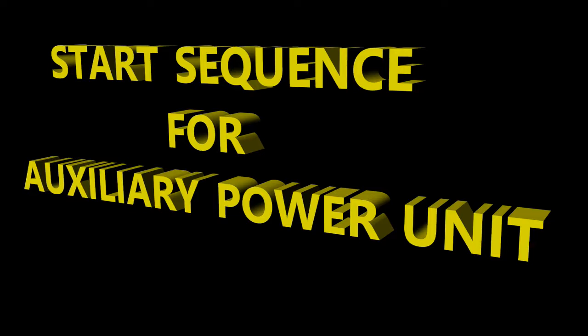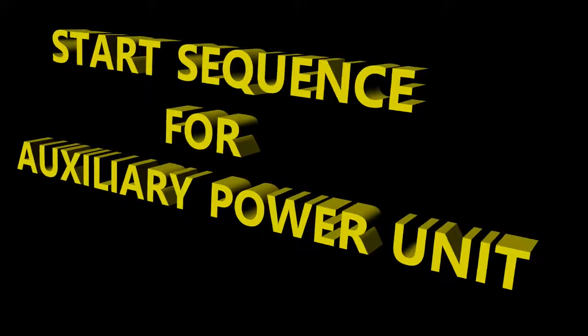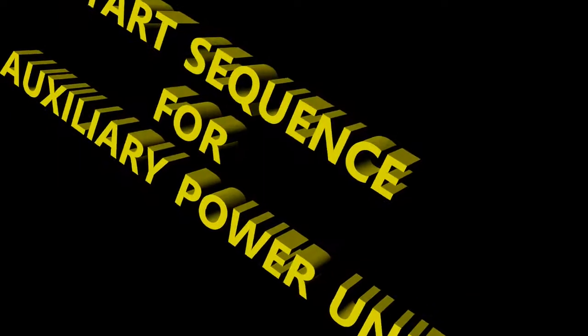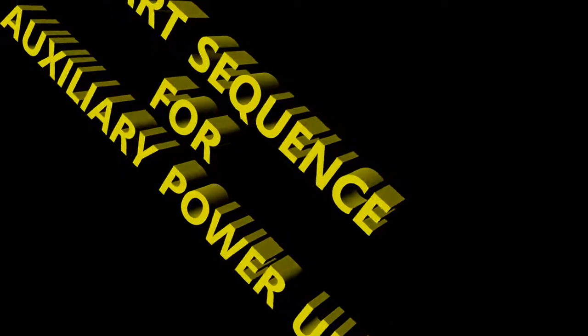At 30% speed, the electronic control box is going to cause what? It's going to cause a de-energizing of the fuel flow divider solenoid. At 50%, what happens? The start contactor is going to be de-energized. That switches off the starter motor, like I said a bit ago.